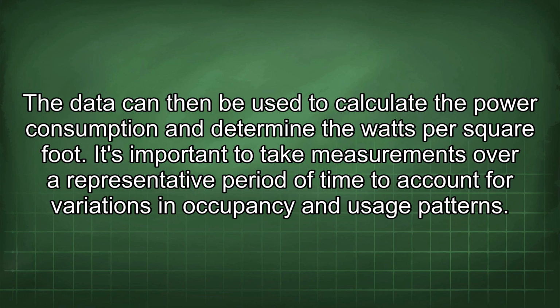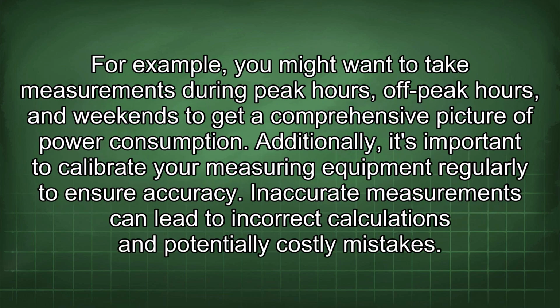It's important to take measurements over a representative period of time to account for variations in occupancy and usage patterns. For example, you might want to take measurements during peak hours, off-peak hours, and weekends to get a comprehensive picture of power consumption. Additionally, it's important to calibrate your measuring equipment regularly to ensure accuracy. Inaccurate measurements can lead to incorrect calculations and potentially costly mistakes.